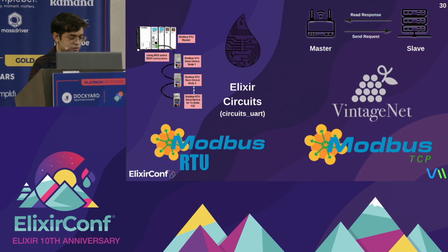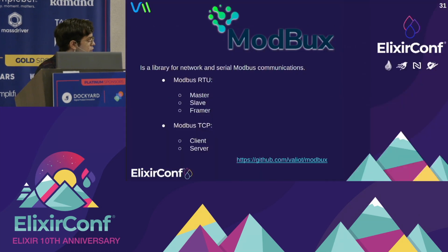So we could merge or mix these packages, and we created this library, which is called Modbus. This library supports serial and network Modbus communication. We implement both behaviors: master-slave, which is the communication on a bus in serial communication, and Modbus TCP, which uses client and server behavior.